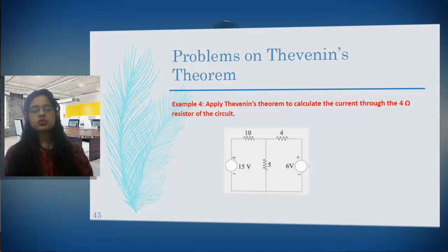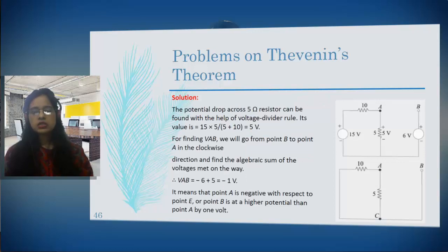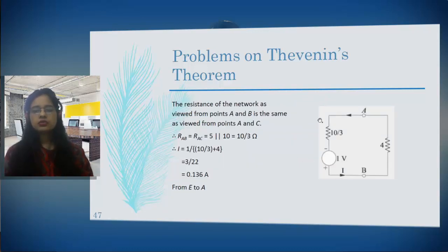For that, you will require Thevenin's voltage and Thevenin's resistance, that is VOC or VTH, and RTH. Initially you draw this, and keep in mind to find the value of VOC or VTH and the value of RTH. Once these values are found, directly connect the load resistance across this, and then find the current.